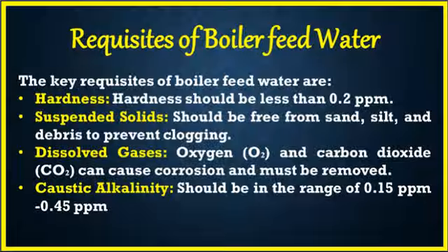Now, for steam generation purposes, what are the requisites of boiler feed water? Some key requirements of boiler feed water are: first is the hardness. The hardness of boiler feed water should be less than 0.2 ppm. That means it should not contain a high amount of calcium and magnesium salts. Second, suspended solids. It should be free from sand, silt and debris to prevent clogging in boilers.